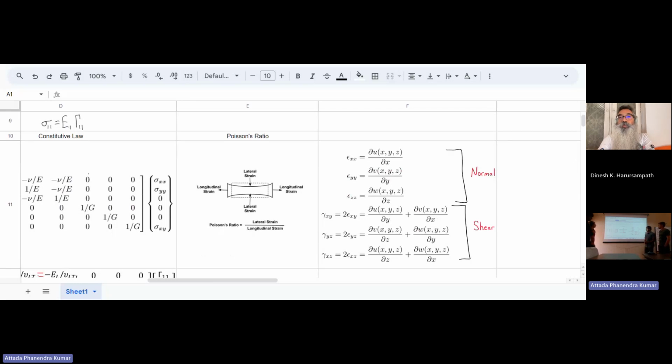We're relating strain to strain. This equation is not necessarily the correct equation, but it always used to include the diagram. We're showing how causing a strain in one direction, where this is the x1 direction, will cause a negative strain, straining inwards in the transverse direction. That's why the equation ends up being lateral strain over longitudinal strain. This should have had a negative sign, since the directions are opposite.